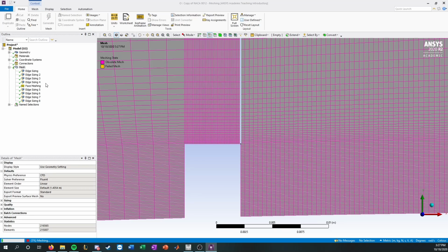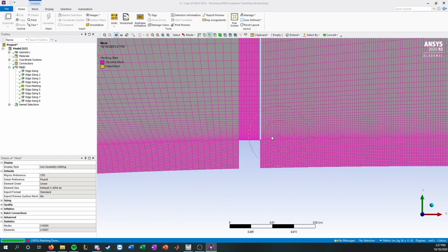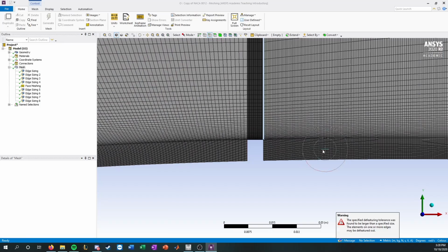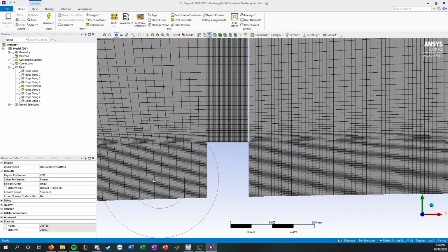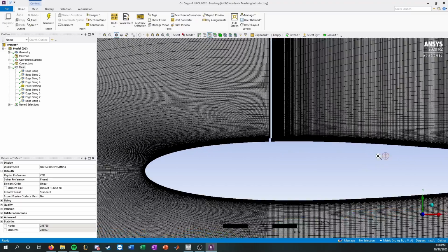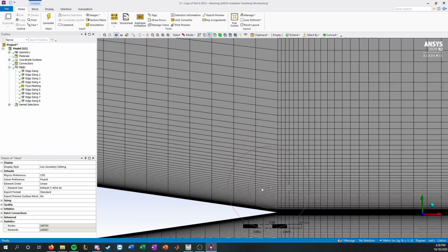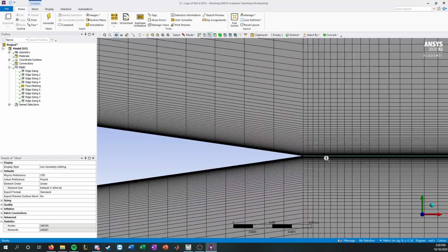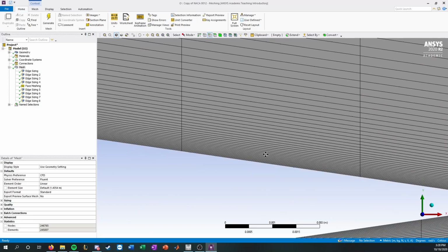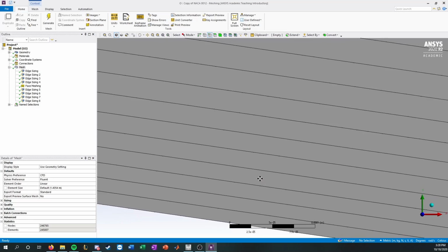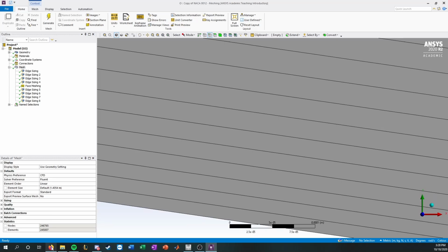I could have done this on my own prior, but I didn't want to have to play around too much. But here we've added this area and we've meshed it. So if you're doing something similar, keep in mind that everything, especially in a structured mesh, which is ideal, has to match up those numbers of divisions. And look, this looks much better. There's still a shift in volume, but not as bad as it was prior. And as for Y plus, this is good. So this is 2.5 E here.